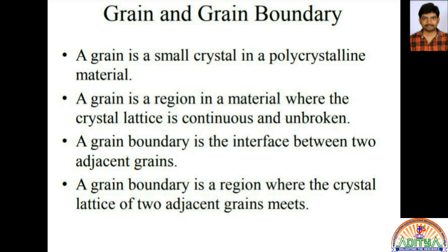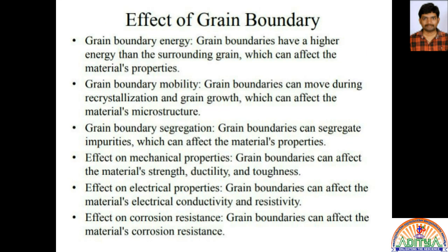So first one, if you consider grain boundary energy, grain boundaries have a higher energy than the surrounding grain, which can affect the material properties. That is the main important thing. And next one is grain boundary mobility. So grain boundaries can move during recrystallization and grain growth, which can affect the material's microstructure too.